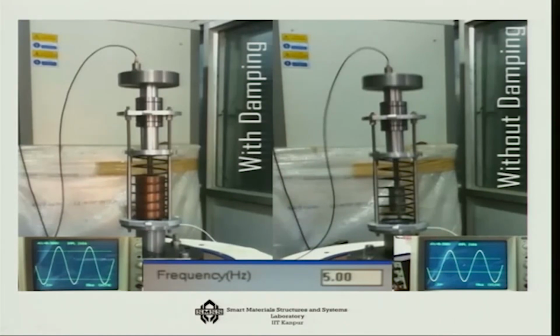One is a system which has a damper. It is like a damper in the form of a copper block here, which converts the oscillatory motion. Inside the copper block there are magnetic blocks, and as the magnets move inside the copper block, they generate eddy current, and thus the vibration is converted to electrical energy in the copper block. So, that is kind of a damper.